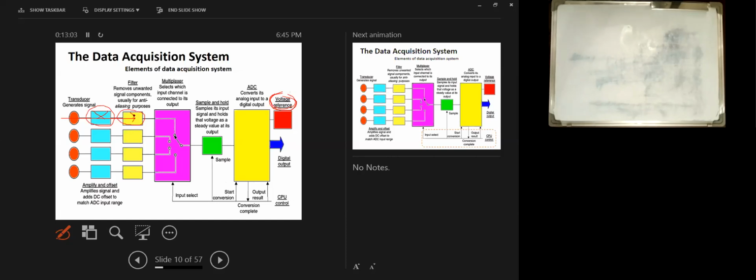Basically, you remove some of the frequency components and you keep others. What is the purpose of filtering in this case? As Yazan said, one purpose of filtering in this acquisition system is to remove the noise. For example, you might know that your input signal has a frequency content that is from 0 to 1 kilohertz. So you want to make sure that only these frequencies are passed to the A to D.